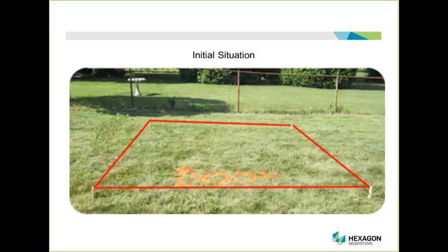So this would be, I guess, just a very simple 4 stakes on a parcel of land that the surveyor's put in. Once I've done a control line setup, and I'll explain what that is later because some of you may not know, I can get the coordinates of the points, but I'll only get them in 2D because the control line setup only gives me 2D coordinates. So I need a height.